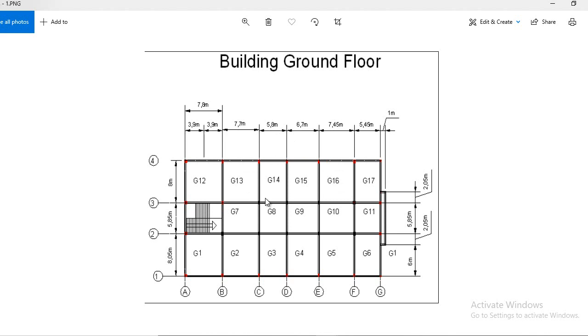And similarly, by shuffling the live load pattern, it will also cause unbalanced moment. And similarly, due to lateral loading, there will also be unbalanced moment. Remember, you have to run the analysis for lateral loading, and similarly for the live load patterns, which we already explained in my lectures from lecture number 3 to lecture number 9 in the equivalent frame method, and you see their effect, how they cause the unbalanced moment.